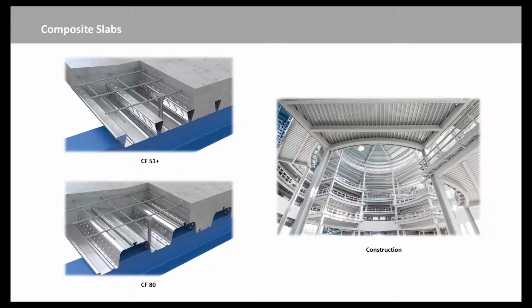The cross-sectional area of steel sheeting that is needed for the construction phase often provides more than enough bottom reinforcement for the composite slab. It is then usual to design the slabs as simply supported. The concrete is of course continuous over the supporting beams, and the sheets may be as well. These simply supported slabs require top longitudinal reinforcement at their supports to control the width of cracks.